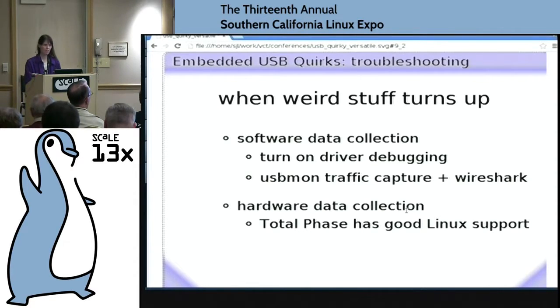So I'll go ahead and finish the little case study that I mentioned about this Bizarro printer, where it would go catatonic if you turned off the USB host while it was talking to it. It turned out that this was actually a pretty deep hardware problem that we never found. I even used the Total Phase to sniff it, and everything was proper from the host side when it was coming up the second time and the printer refused to finish enumeration.